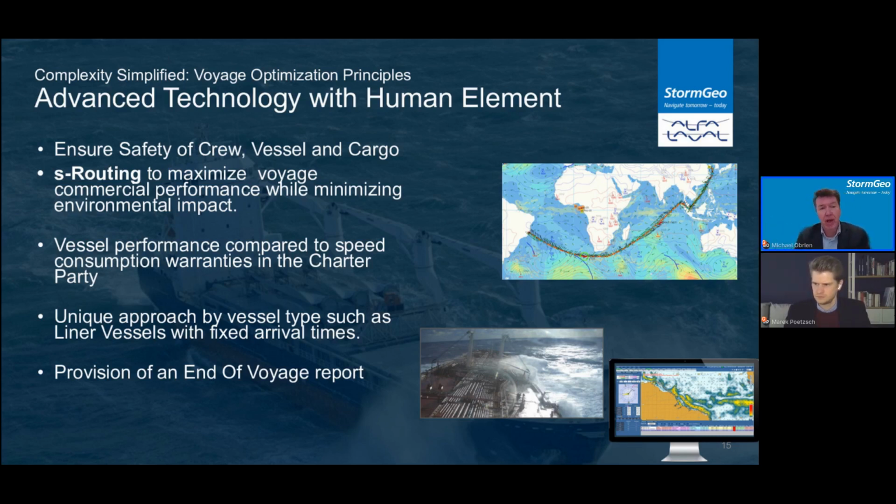You might have a fixed arrival time. There are different flavors on how to apply voyage optimization to get the most out of it. And one of the key things it does is allow us to provide information to users with regard to how a vessel is performing against a charter party. This can be very important, and it'll have some implications when I talk about the BIMCO clause in a few moments.